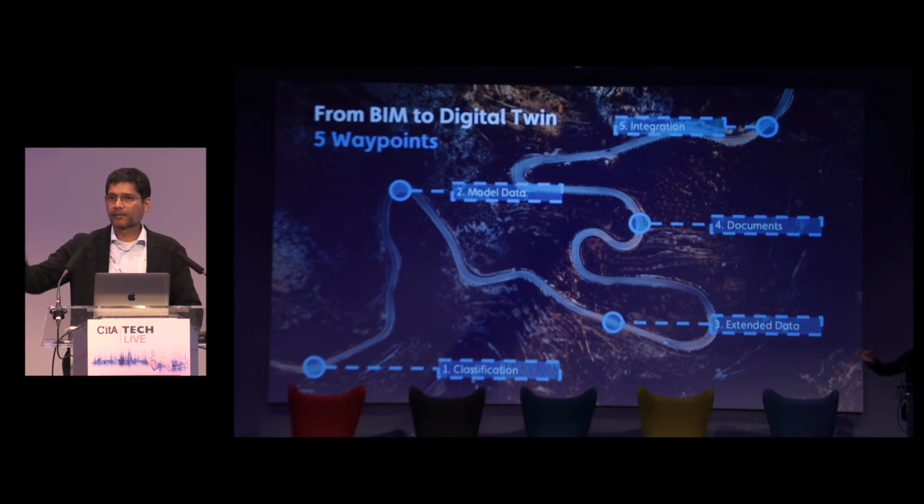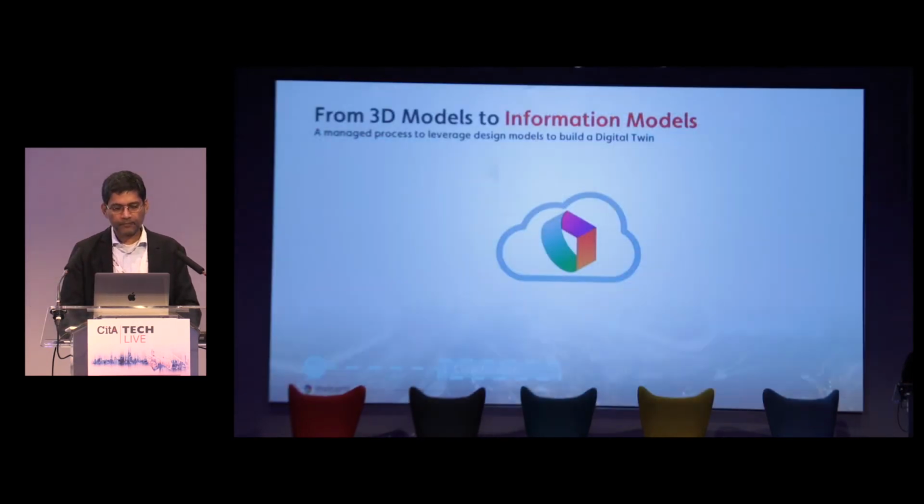In the past, a commissioning engineer would put a tag on a particular sensor value, which you would never know what it is. Today, if it is Haystack or Brick coded, you know exactly that sensor value represents an airflow or the damper position of this particular piece of asset, which means you can integrate that back into your digital twin. So it's getting easier, but we've got to have the infrastructure to make it happen.